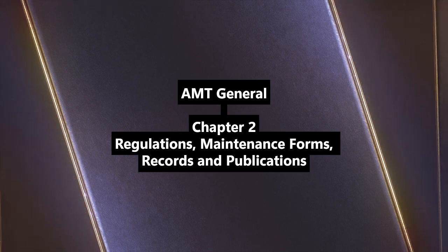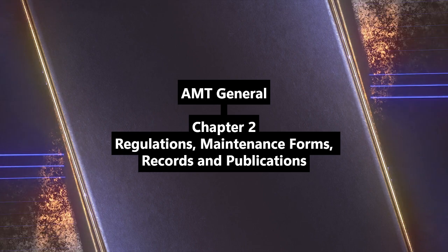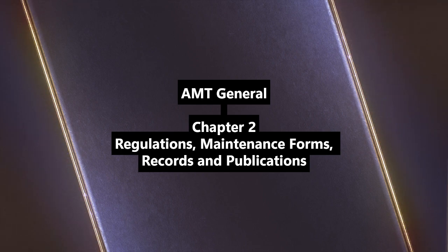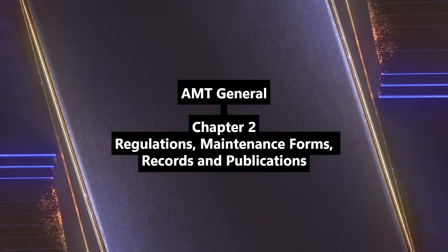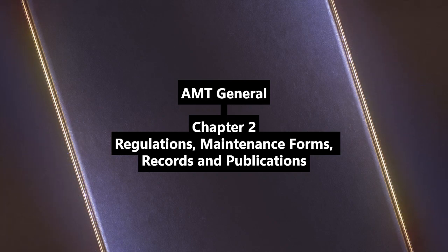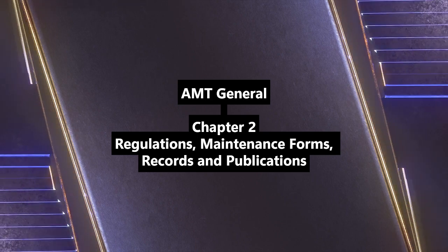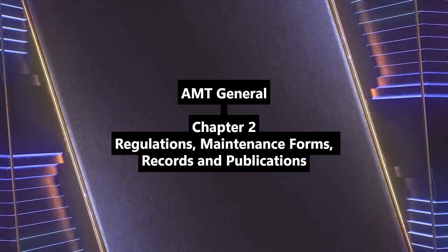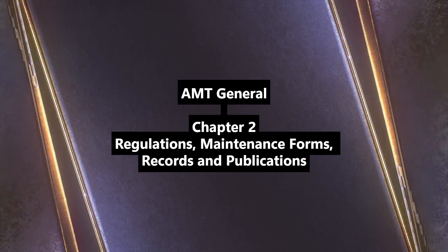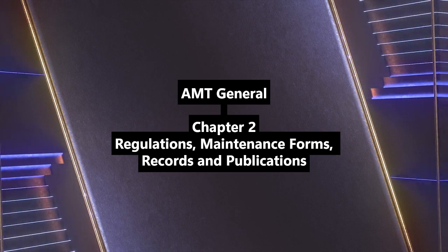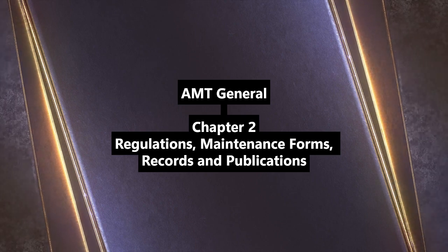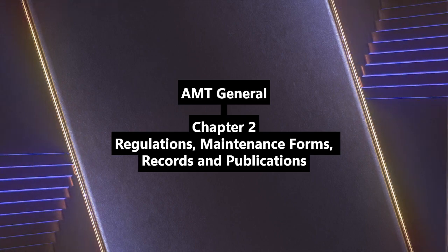It gets very specific: CG limits, fastener strength, control design, everything. Okay. Then the big planes. That's 14 CFR Part 25 airworthiness standards, transport category airplanes. Think aircraft over 12,500 pounds max takeoff weight. Airliners, cargo planes. Commercial aviation. Exactly. Though they don't have to carry passengers to be Part 25. It follows a similar structure to Part 23, just scaled up for larger, more complex aircraft. And helicopters have their own parts. They do. 14 CFR Part 27 is for normal category rotorcraft, smaller helos, 9 or fewer occupants, up to 7,000 pounds. Structure mirrors Part 23.